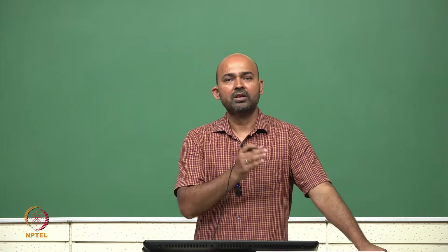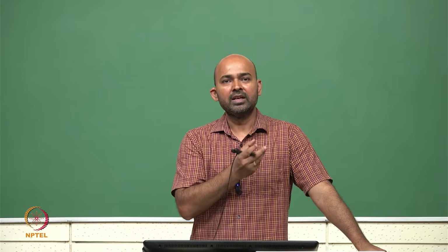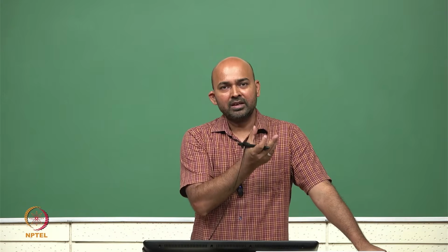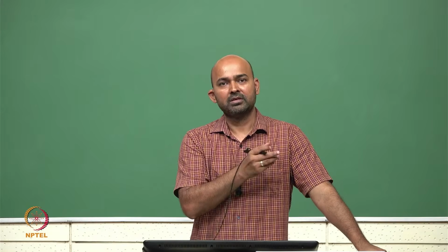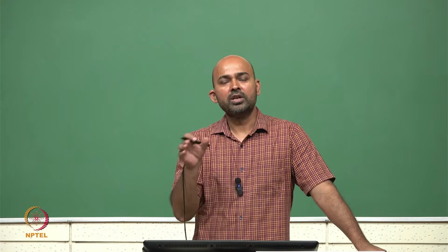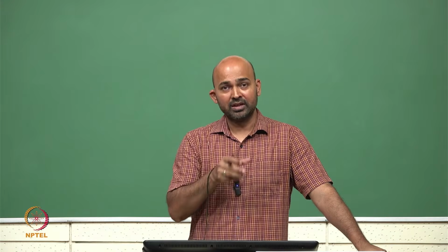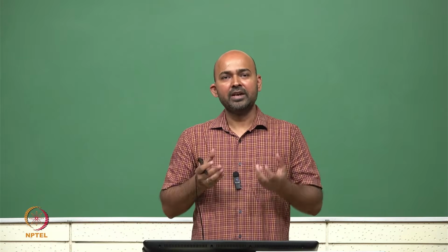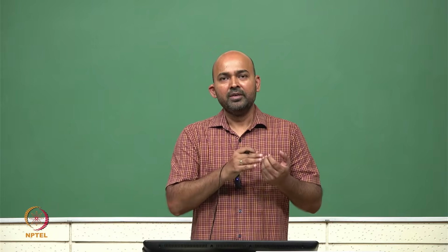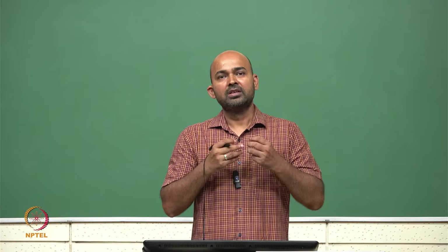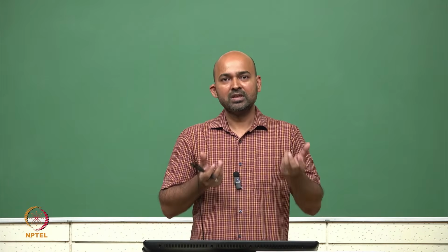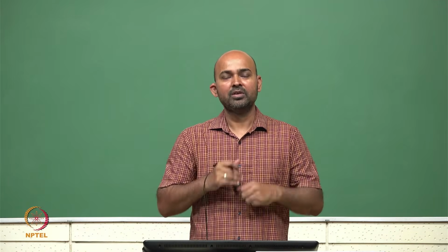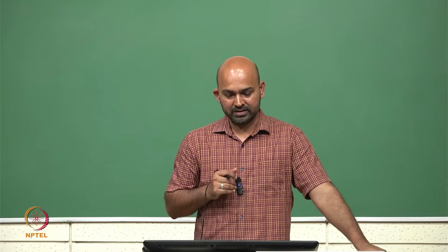So we have, let's say, one voltage source and one current source. We can take one at a time. We take the voltage source as the actual source, and short or open all other sources. For the other source, the current source, we open circuit it; we do not short circuit it because the internal impedance of an ideal current source is very high, let's say infinite. The internal impedance of an ideal voltage source is 0, so we short circuit it when we want to replace it with its equivalent resistance.